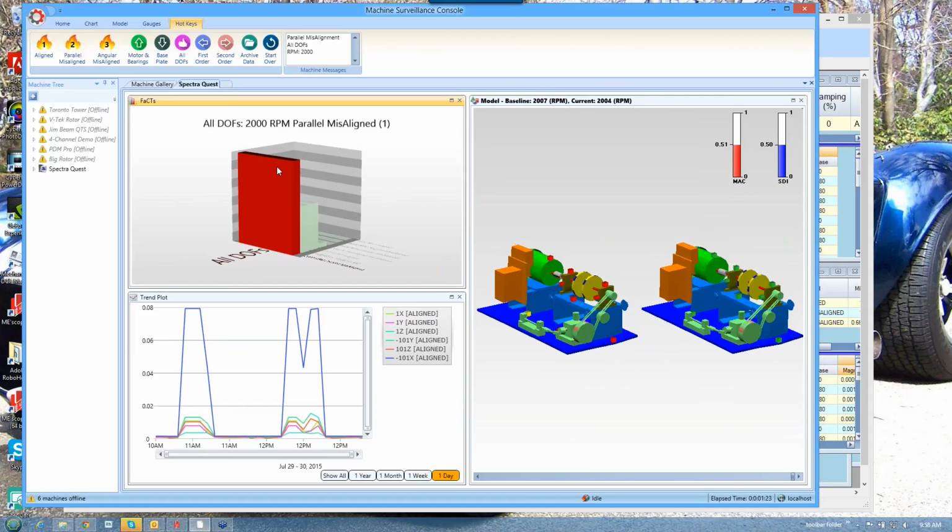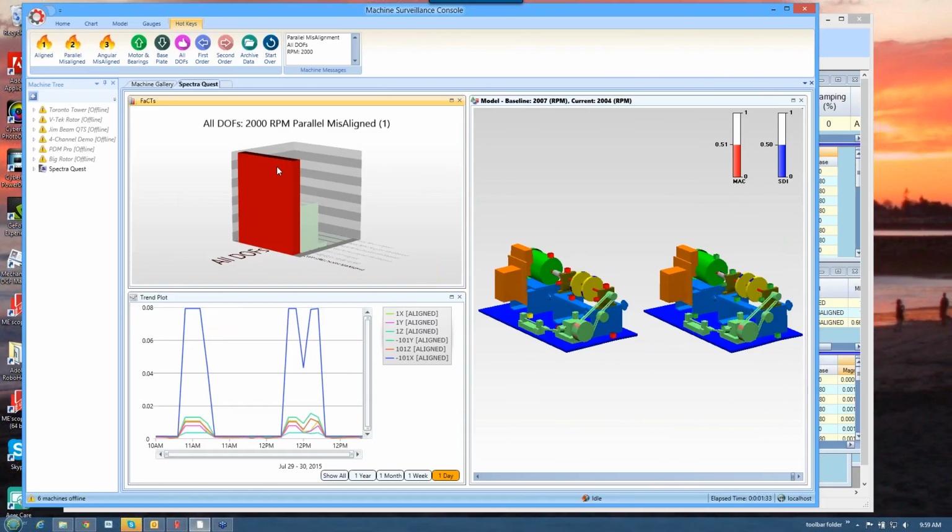So you can integrate right in the shape table from G's to inches or millimeters, centimeters, whatever units. MeScope will do that, and we could put that command into one of the macros where we're loading up the shape data into the appropriate shape tables, either for archiving into the database or for,